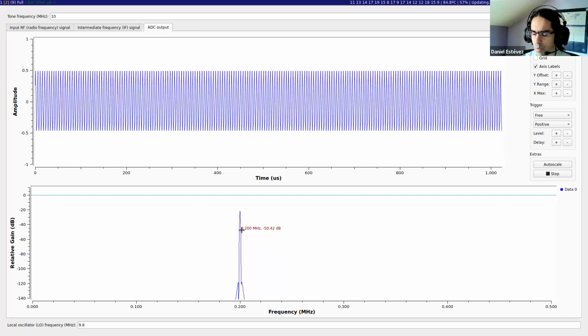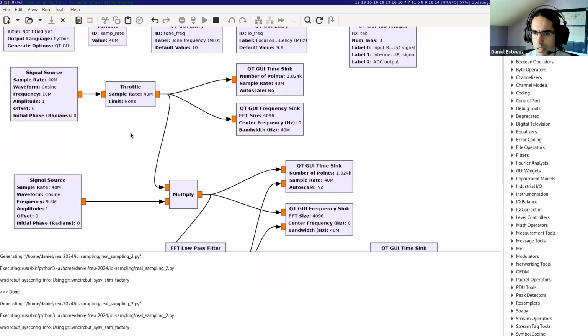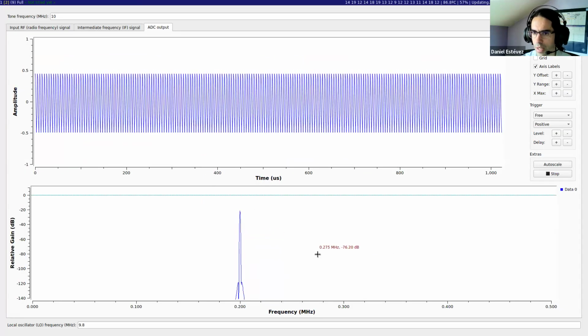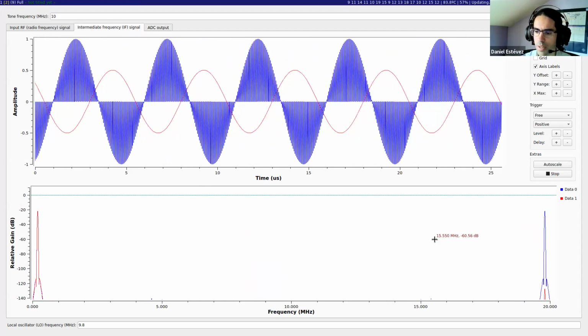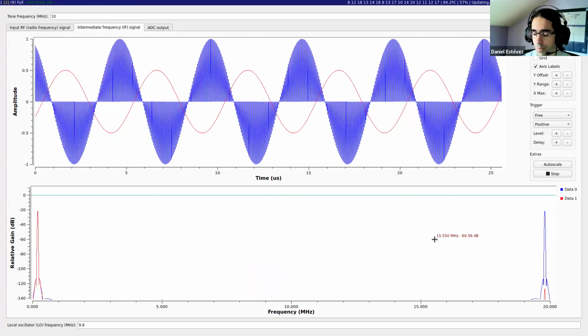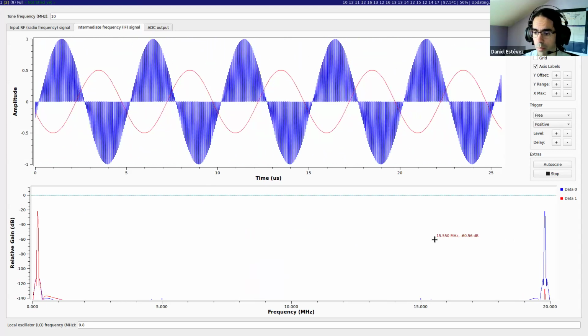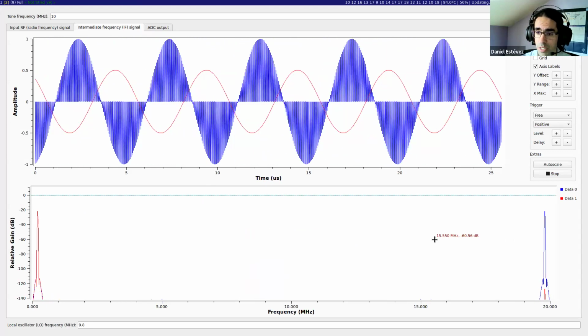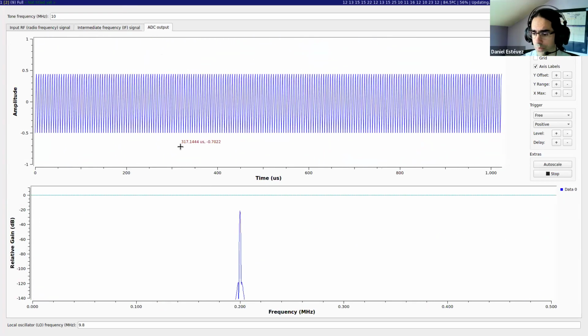So anytime we want to do one of these shifts, if we use the same thing as before, which is multiplication by a cosine function, we will get the shift we want, but also an unintended shift that needs to be removed by a filter. And having to use a filter is inconvenient because filters are expensive, speaking about computation, CPU power.